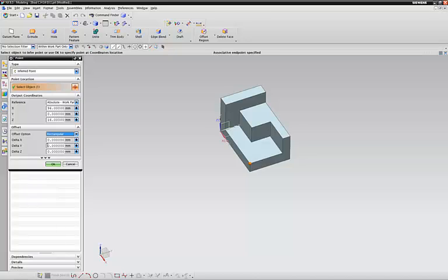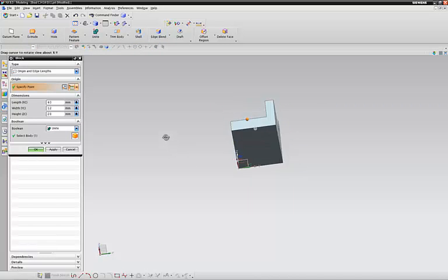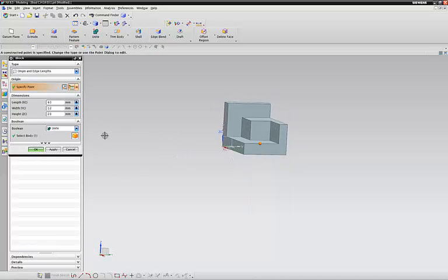So in the Y direction, 23 minus 8. No, minus 4, because no, I'm right, it is an 8. Because our radius of that cutout is 8, and that's how far back from that dimension, because it's dimensioning from the center point. So it puts us right where we need to go, since we'll be cutting in a positive direction.